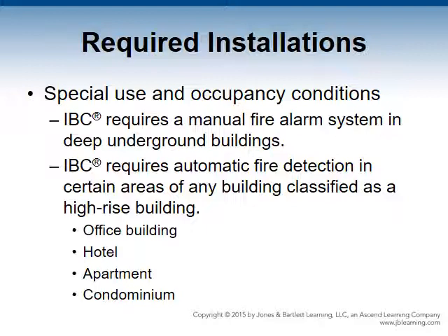IBC requires automatic fire detection in certain areas of any building classified as a high-rise building regardless of use classifications, such as office buildings, hotels, apartments, condominiums, and telephone switching centers. Both model codes require automatic fire detection in the building if it is considered a special amusement building.